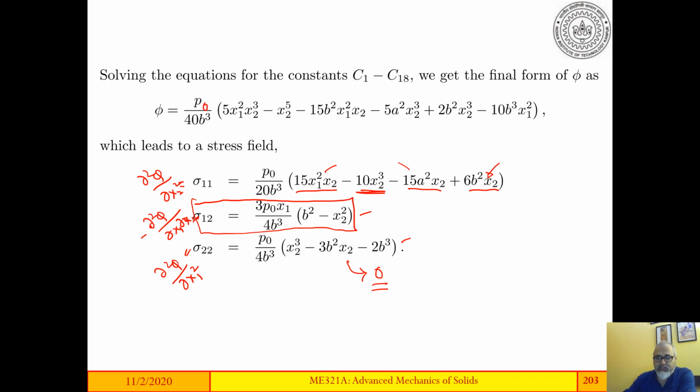However, for deep beams, this solution will work, while Euler-Bernoulli will not work because of this term, which increases as the cubic root of the depth. So the Euler-Bernoulli beam theory works for a thin beam very well, and it does not work for a deep beam that well. Of course, sigma 2,2 is not there.